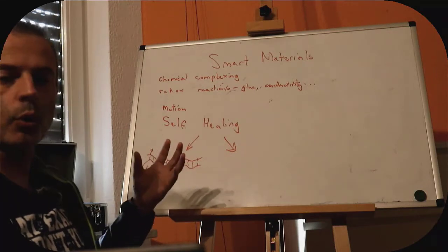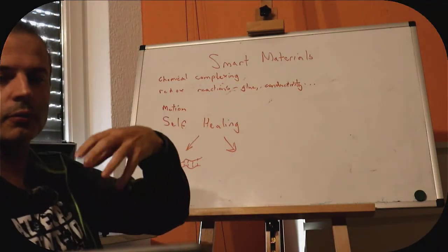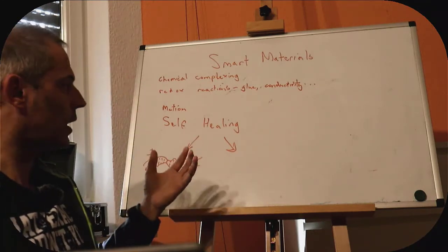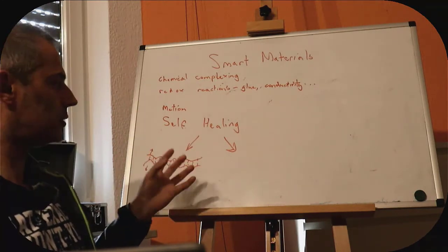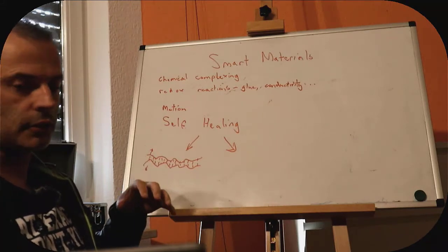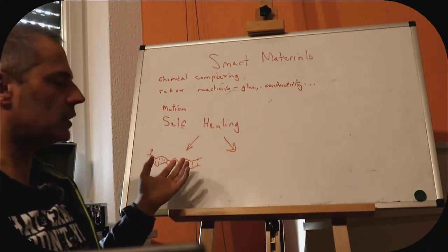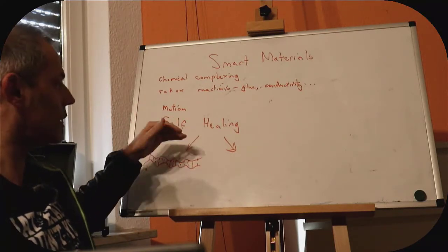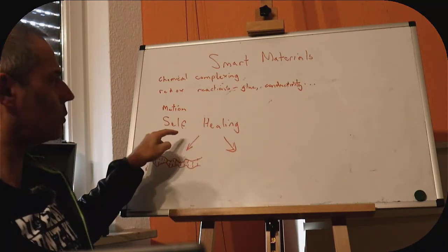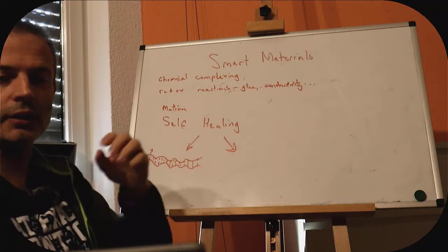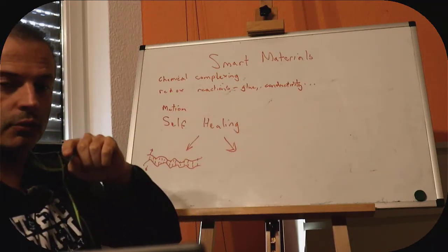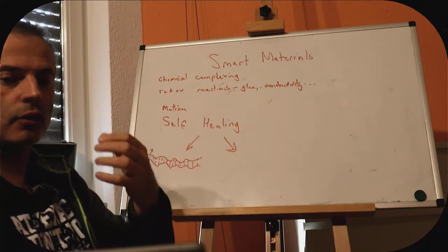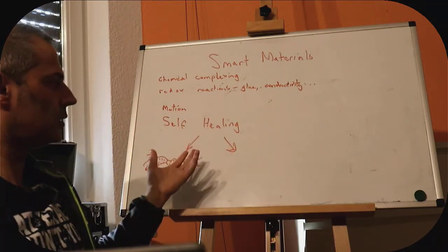So instead of pouring a polymer into your electronics and have it insulating it, it is better under certain circumstances to not do that, to use a liquid instead. If we use a liquid, the advantage is if we have a bad event, if we have a high voltage event where one side is positive and the other side is negative, and we have a spark jump across through our liquid, it will form a trail of more conducting material, depending on what it is.